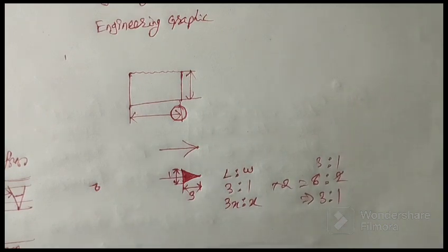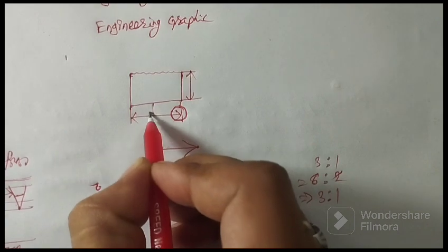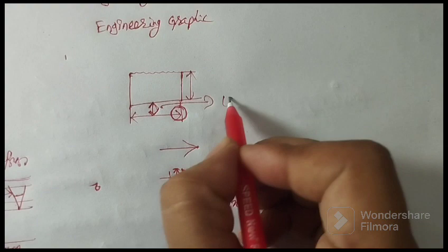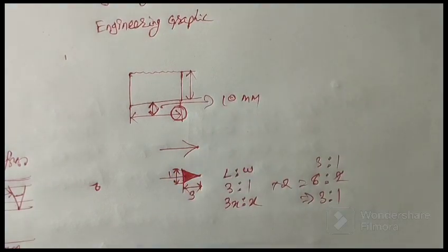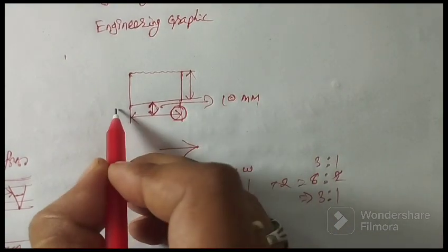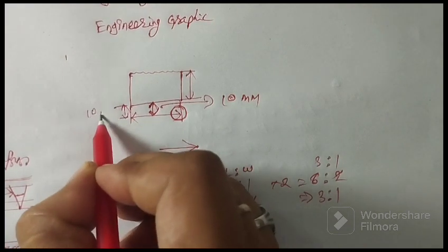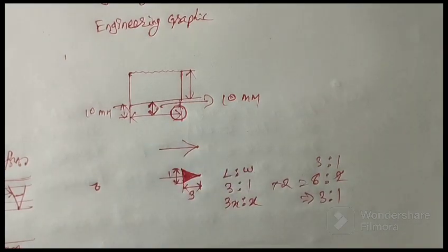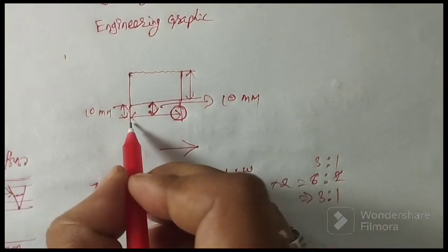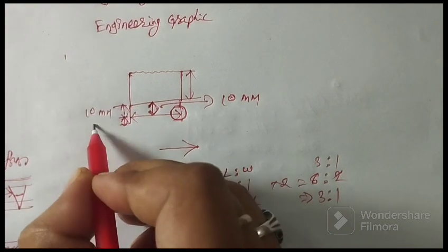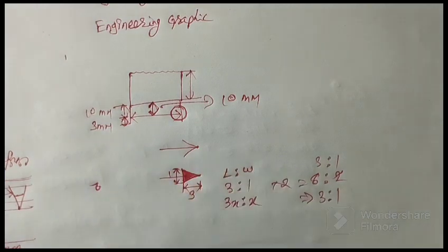Now, that is about the arrow. Next, whenever you write an arrow or the dimension, see that this length is not more than 10 mm. This length means from here to here, the head of the arrow, do not exceed more than 10 mm. And after the arrow, this excess length should not exceed more than 3 mm.